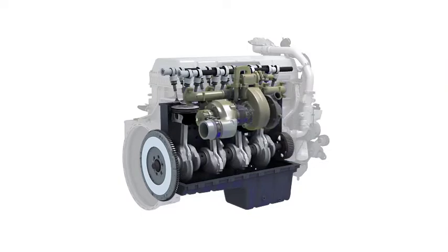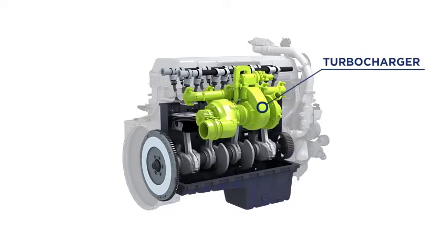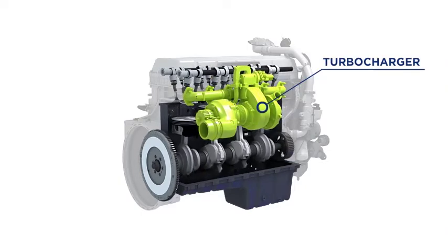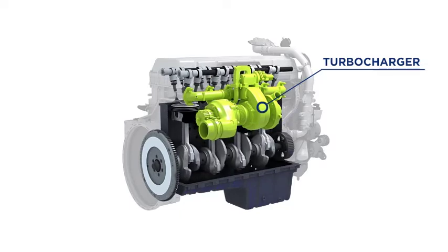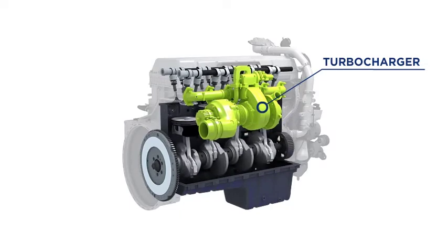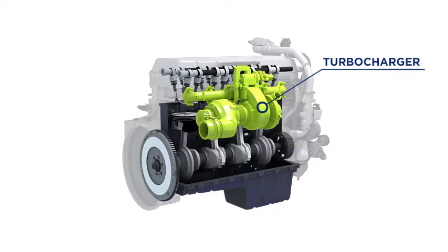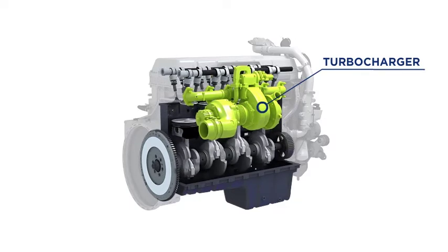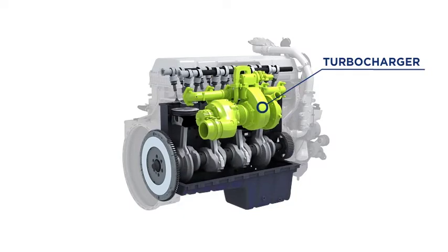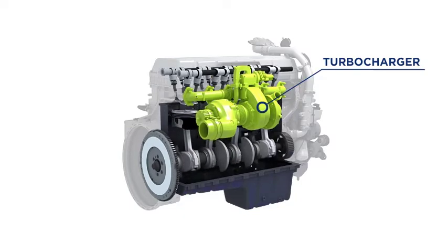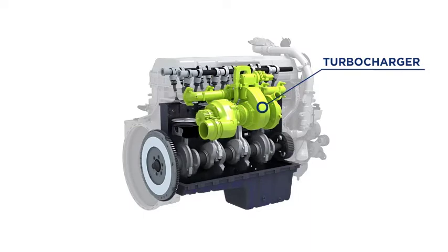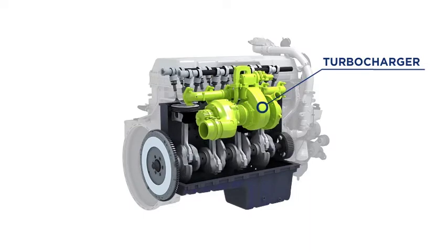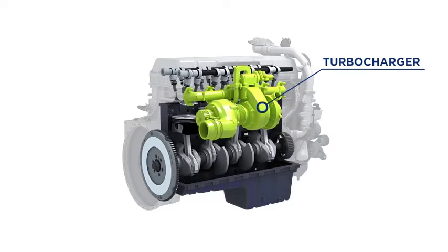Diesel engines, and some modern gasoline engines, utilize turbochargers to increase both power and fuel economy. A turbocharger uses the energy in the hot, expanding exhaust gases to drive a turbine that forces more air into the combustion chambers. This increases the engine's efficiency and power output. The turbo bearings are pressure-fed with oil from the main oil gallery. Keeping this bearing lubricated and free of deposits is critical to the reliability of the turbocharger.